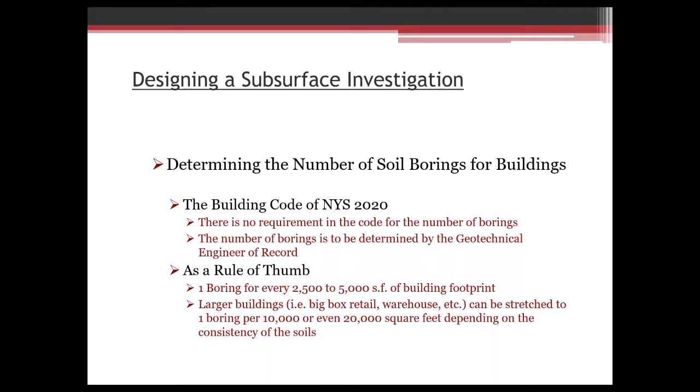Large warehouses may approach 100,000 square feet or even greater than that. We can start stretching the number of borings out to one boring for every 10,000 or 20,000 square feet. And a lot of that depends on the consistency of the soil. So one thing that the geotech engineer typically does is go through and review the soil conditions that they think are going to be in that area from soil maps or other sources that are publicly available, and even the history of the company that they work for.